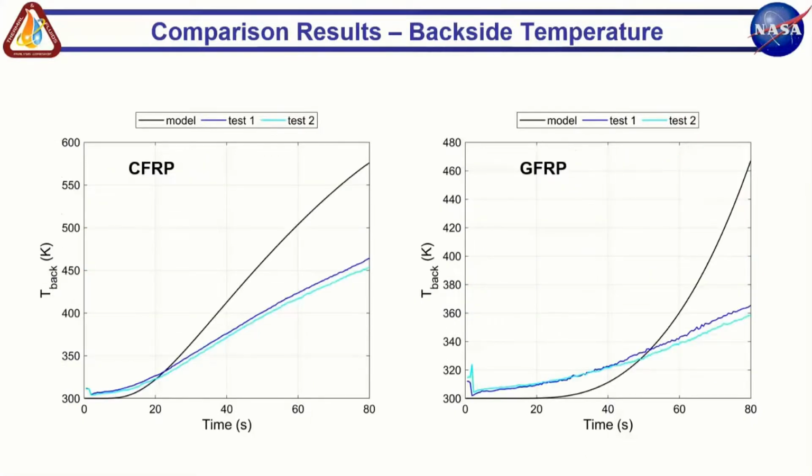The backside temperature matches a little bit better, but overpredicts the final backside temperature, and could indicate that our thermal conductivity is a little bit too high.